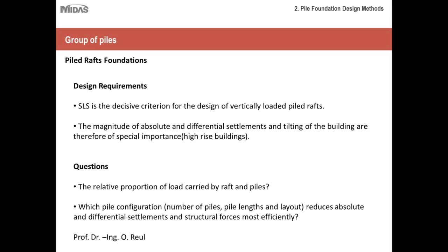Or if you have a high-rise building that is tilted and then you have a strong lateral wind load onto it, it will amplify the effect onto the foundation. So since we cannot afford to have these kinds of settlements, the serviceability limit state is the most important criterion that you should meet when you are dealing with pile raft foundations.